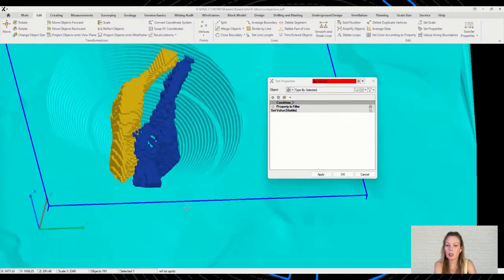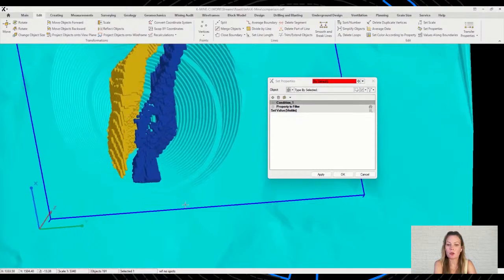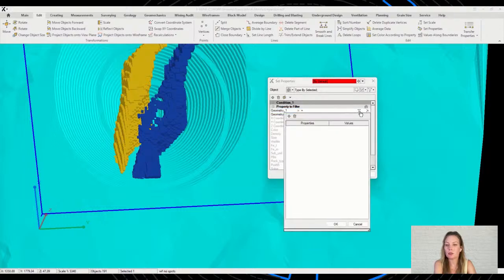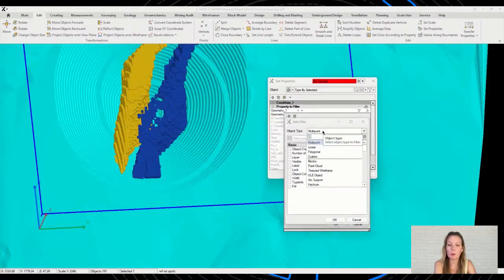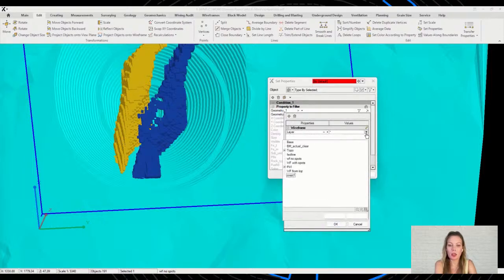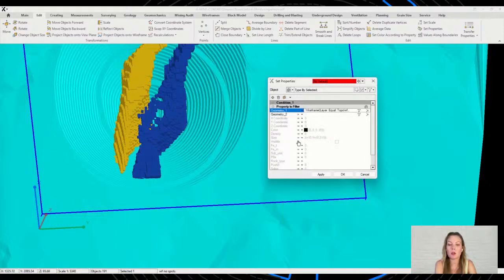Next, we have to calculate the excavation volumes for each of the options, and to do this, we use the set property command with the block model active and limited to 2 frames, above the design one and below the actual one. This task is multifunctional and can be used both for block model and for other complex objects, for example, for working with a point cloud. We follow the sampling instructions step by step and determine the necessary layers in which our frames are located.